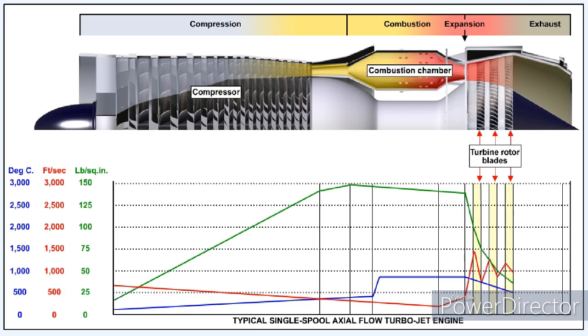Succeeding nozzle guide vane stages will continue to convert the pressure and heat energy in the gas stream into kinetic energy, and the turbine rotor stages which follow them will convert that kinetic energy into mechanical energy. The gas stream is then directed into the exhaust nozzle, where the velocity decreases at the expense of a small rise in pressure. This decrease in velocity assists in maintaining the losses in the jet pipe due to turbulence at a minimal level. Finally, as the gas passes through the sharply convergent propelling nozzle, the duct shape causes a distinct increase of velocity, and the pressure of the stream drops to that of ambient in response to that increase.